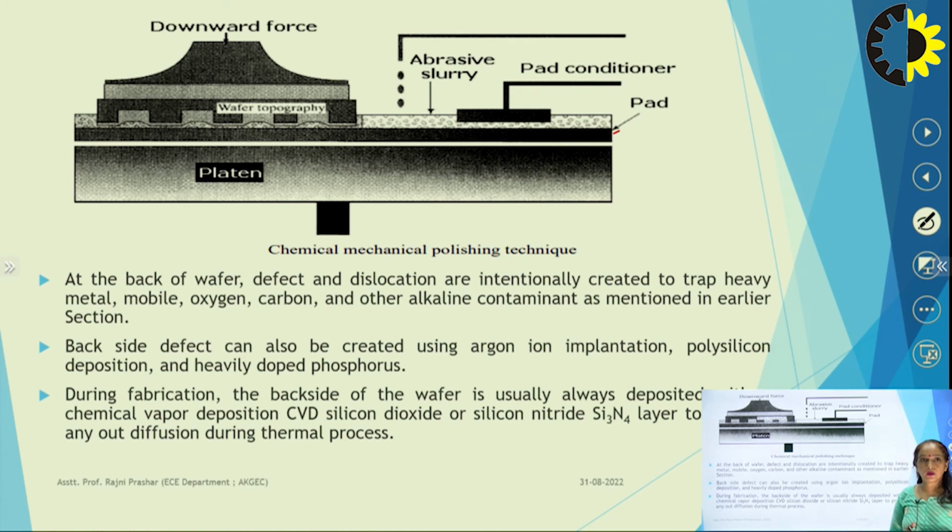They will lower the breakdown voltage, and finally lead to device breakdown. So we have to collect these metallic impurities throughout the process. Sometimes dislocations are intentionally created, and sometimes we take the oxygen already present during growth as an advantage, so that all these impurities can be collected and don't disturb the device fabrication process.